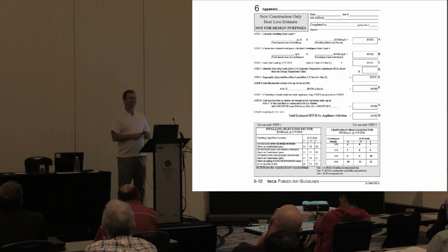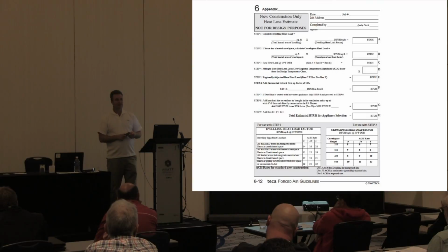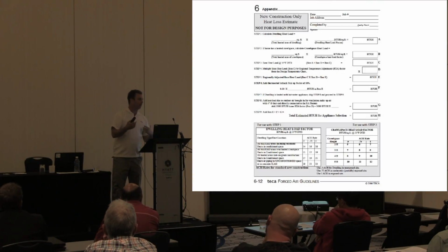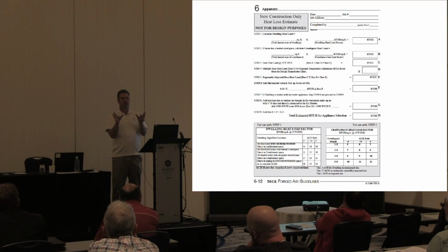So, yeah, David. Do you have any cautions regarding zoning systems? Yeah, there's lots of zoning systems out there. I have one in my house and it works fine, but I didn't try to overcomplicate it. The problem with zoning systems that I've found going to houses that have them, in the 20-something years I've been in the trade, is guys that try to do too small a zone with a big furnace. You start getting into bypass problems and issues trying to leave a master suite on a huge house.